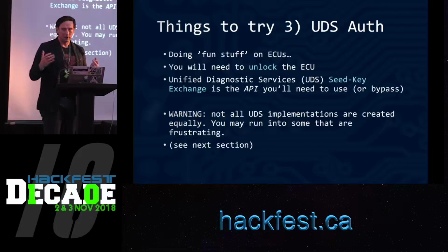So now UDS has things like reflash and dumping memory locations. So all the fun stuff, right? You're going to want to unlock this thing. The authorization is done with something they call seed key exchange. I think if you know cryptography, you're going to recognize it as a challenge response mechanism.